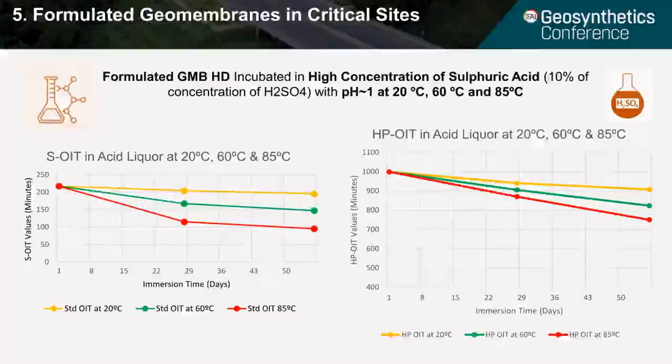The results do not show the typical steep drop in the antioxidant package that a regular geomembrane will present in this environment, as we have seen before, showing that a geomembrane well formulated for a specific site's extreme conditions can ensure long-term performance, minimizing the site risk by creating and customizing the most suitable geomembrane for the project needs.